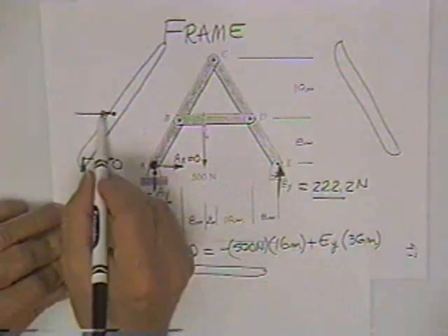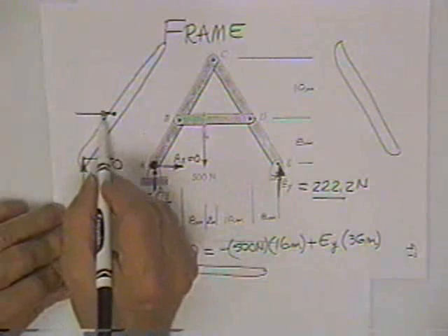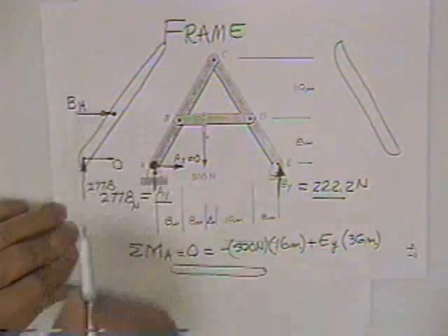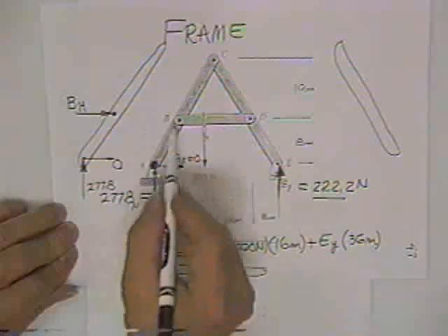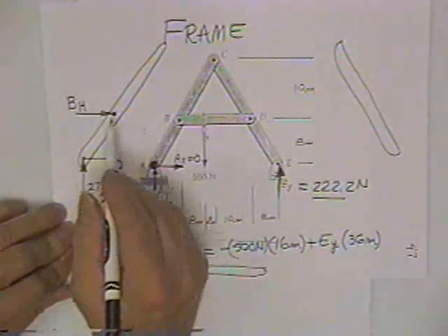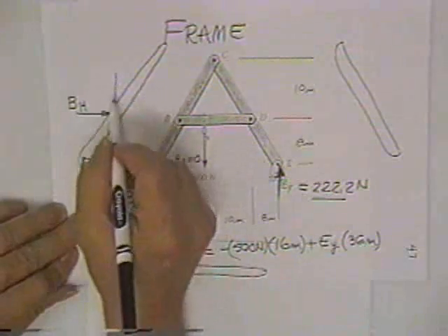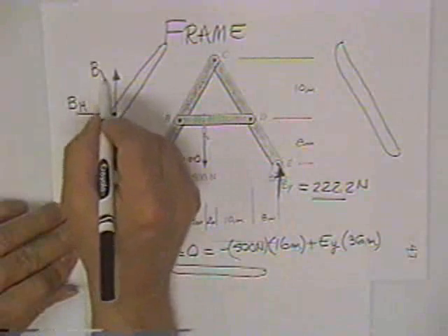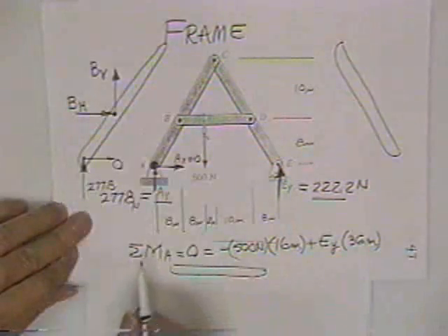However, by separating these two members, you have opened up a pin, and there is the potential for forces. You'll notice I put an arrowhead on it. You'll notice it's probably wrong. You'll notice I gave it a name. Without that, you're doomed. Since you opened up a pin, there are two potential forces at that point. There's my guess for the arrowhead. His name is B vertical.